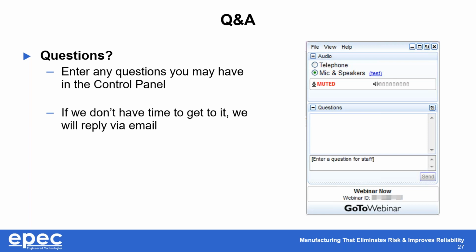So if you need to add some more layers to get what you want, don't worry about adding the time. Once you're into the 8, 10, 12 layers, adding 2 more or 4 more, as long as there's not blind and buried vias associated with it, you're really not going to add any significant time.